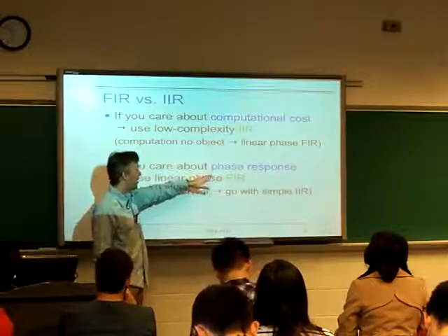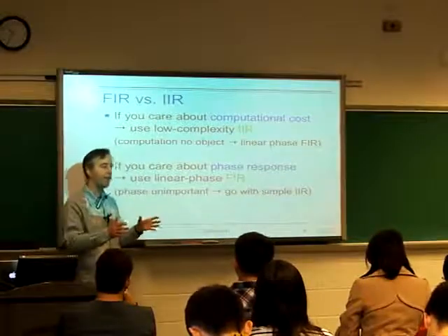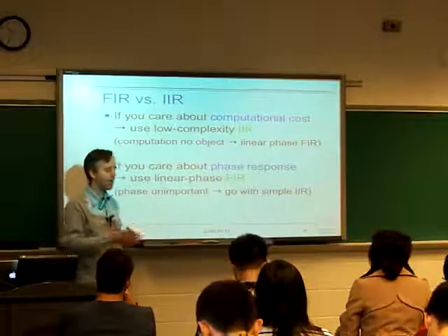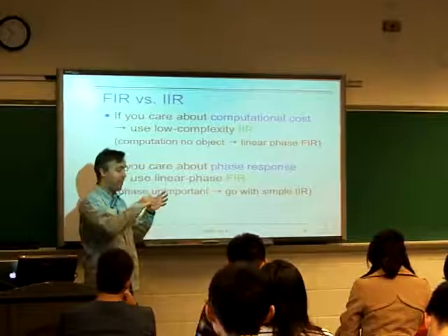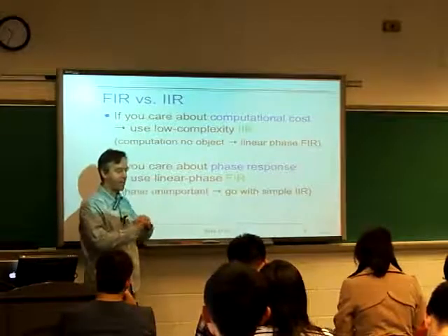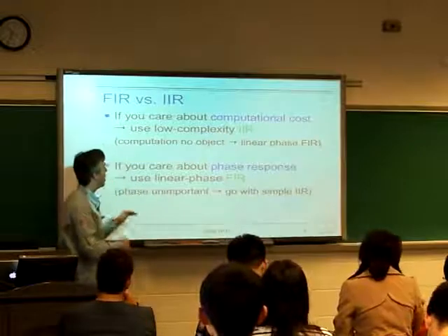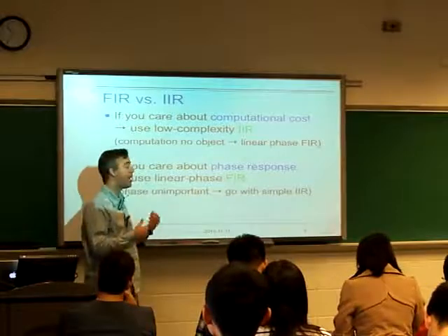So if the phase response is something that really matters, and phase response, remember, is the relative timing of different frequency components. So if you've got something where that matters, for instance, if you care about the shape of a waveform, because the shape results from the phase interactions of the different frequency components, then you're going to want to take advantage of the fact you can get these linear phase FIR filters, and FIR will be your design.